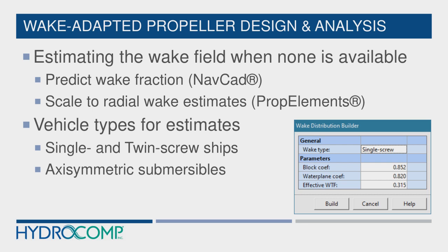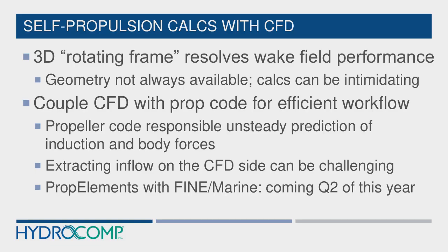So you can do a lot of initial development and get sufficient data for studies on unsteady calculations, noise and vibration, the various pressure pulses very early in the design, and have really good information about whether a propeller is going to be generating underwater radiated noise, pressure pulses for internal noise and vibration, prior to having to do any kind of model testing or CFD studies.